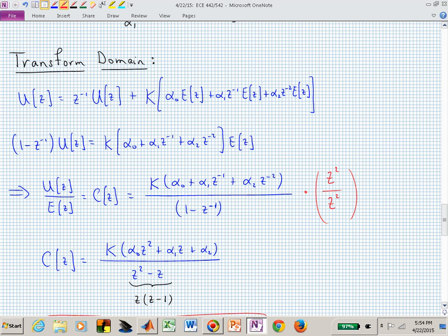And now you could just answer with a P, with an I. So I could just say, give me a P, give me an I, give me a D. It's one of those three. It's a result of one of those three pieces. And what piece gives rise to a pole at Z equal to 1? And what's that equivalent to in the analog case? Remember, Z to the minus 1 is equal to S. Or actually, Z is equal to E to the ST.